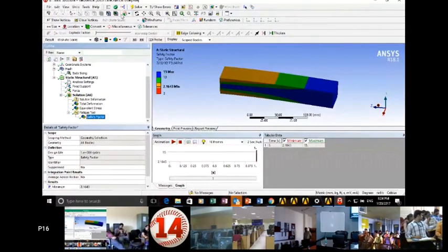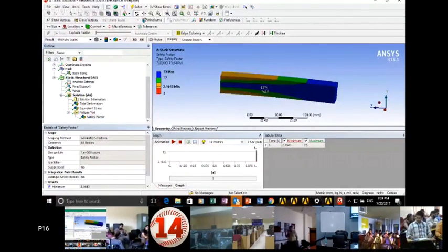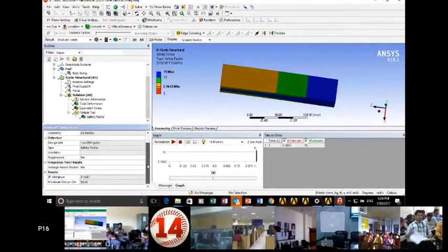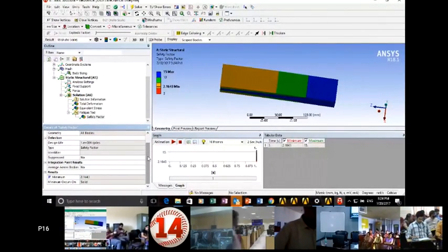By simply solving this, I got a plot for safety factor, which is somewhere around 2.1643. Now, my main focus is that I want to optimize the design taking into consideration a particular safety factor. For example, I want to design my beam model which would have that particular factor of safety. So I'll parameterize that safety factor which I've obtained from the software.